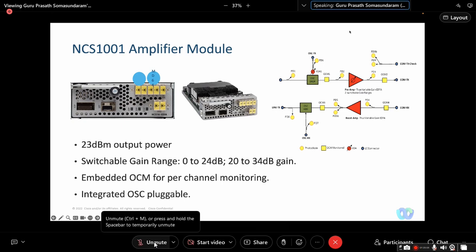It will try to reach a configured or default per channel power and set the gain accordingly. For this DCI solution, it is always used as manual because there is a PSM included. If the amplifier starts to adjust the gain automatically, the power level that the PSM module sees will vary accordingly.